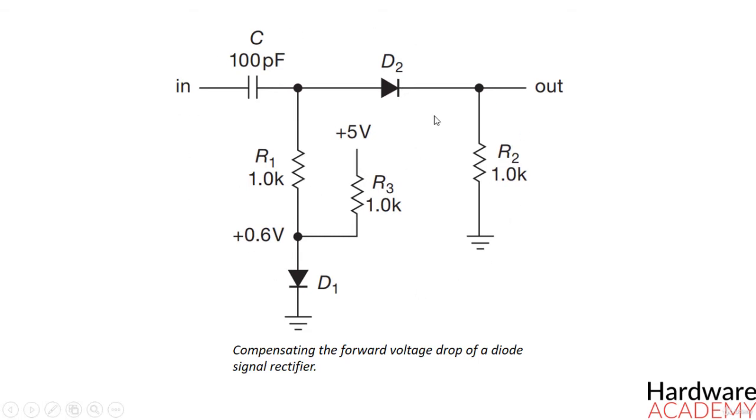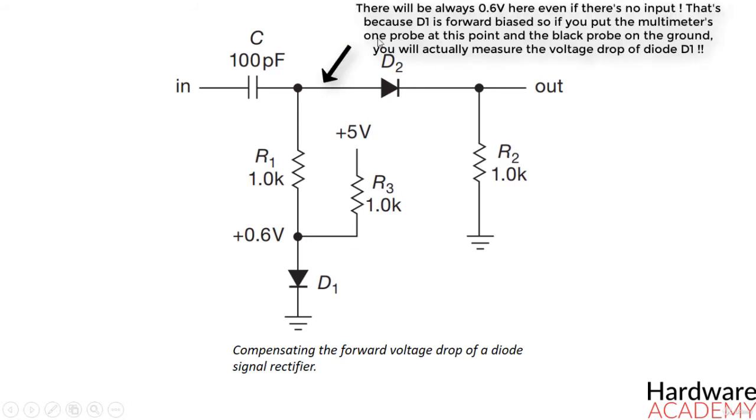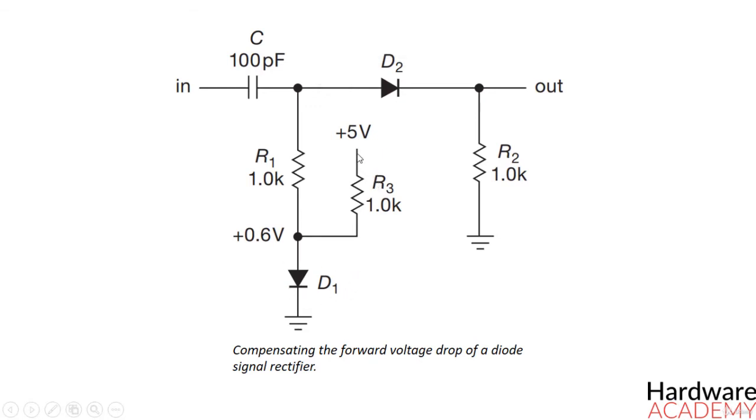In this circuit, diode D1 compensates D2's forward drop by providing 0.6 volts of bias to hold D2 at the threshold of conduction. Using a diode like this to provide the bias has several advantages. The first one is that there is nothing to adjust. The second one is that the compensation will be nearly perfect and changes of the forward drop will be compensated properly. Later we will see other instances of matched pair compensation of forward drops in diodes, transistors and FETs. It is a simple and powerful trick.